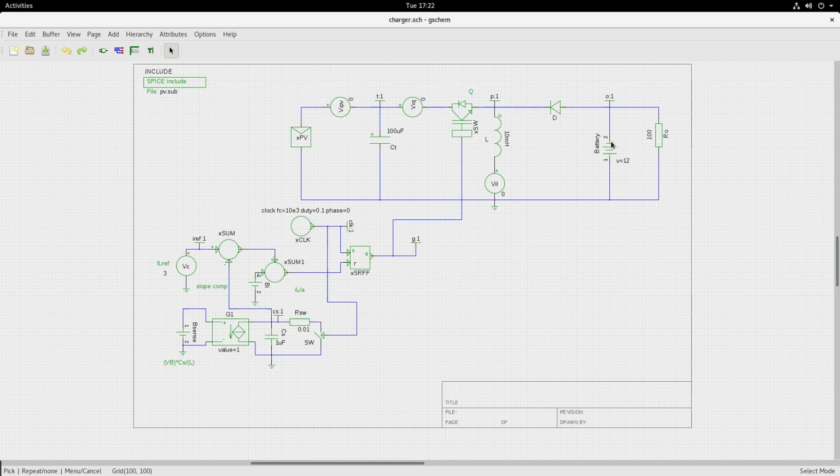Observe that the battery is put in a position where 1 is plus, 2 is minus, because in the buck boost circuit you will have a negative voltage coming across the output, and therefore you have to appropriately connect the battery terminals. And of course the load.